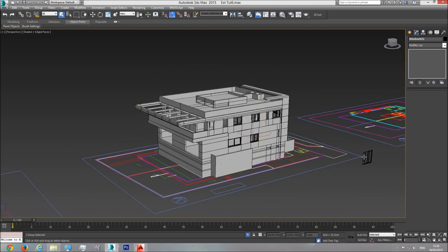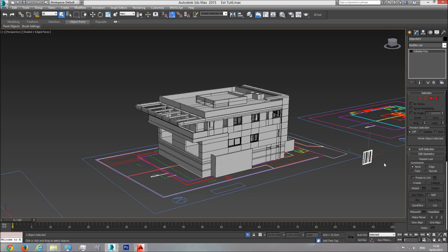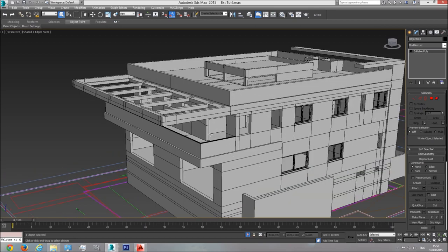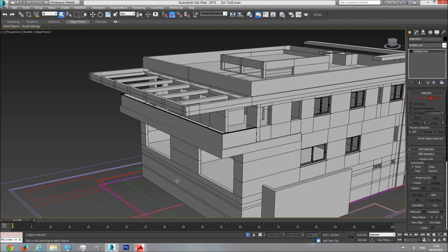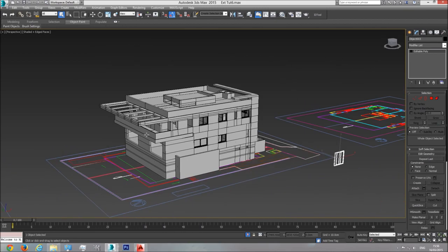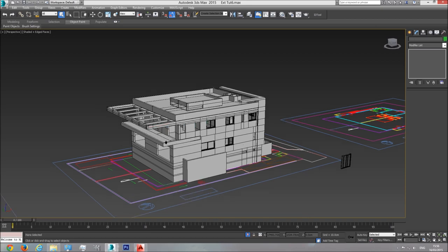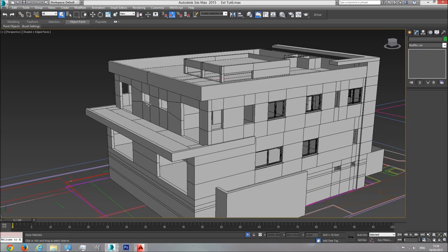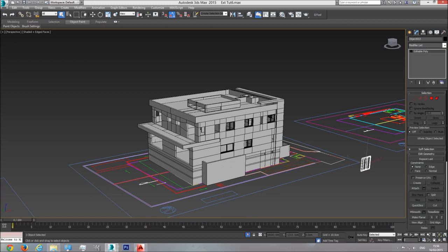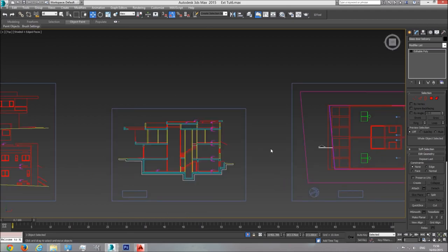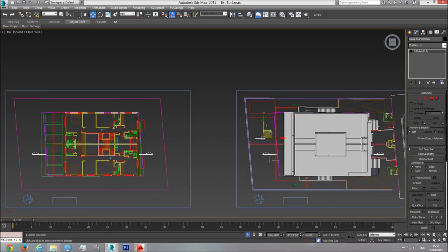Next we're going to place these glass doors in the exit to the balcony and in the exit to the garden. So let's do that. I'm going to hide this railing for now, and let's hide this one for now because it will help me to see the openings. I'm going to take this, let's call it a glass door, balcony, and I'm going to move it in front of the back side of the house, so about here.